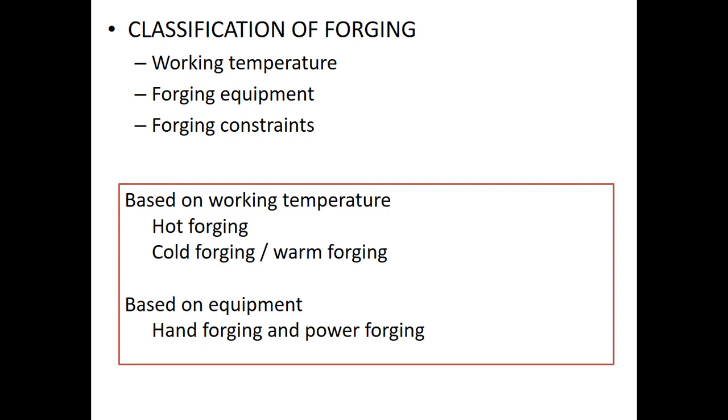It is used only for small parts made in small quantities, whereas power forging is the most common, used in industries for large scale manufacture of small to very large components. In manual forging, impact pressure is applied to the workpiece by hammering. You have done the impact pressure using the hammer, hope you remember. That's why manual forging is also known as Smith forging.